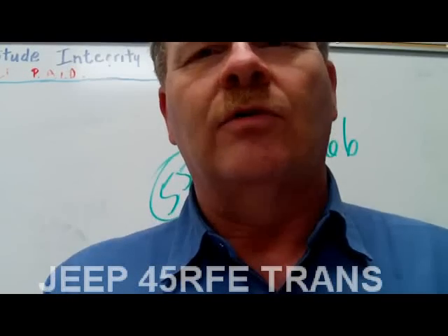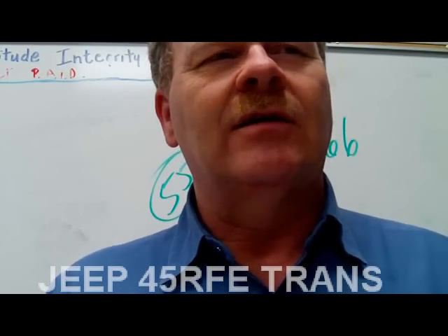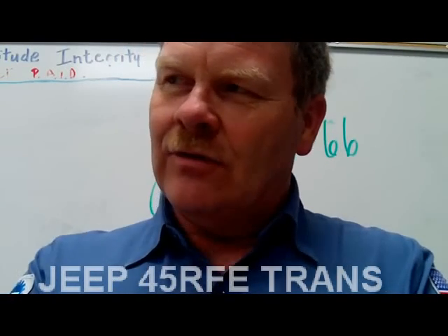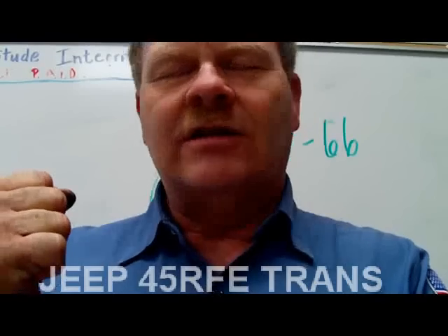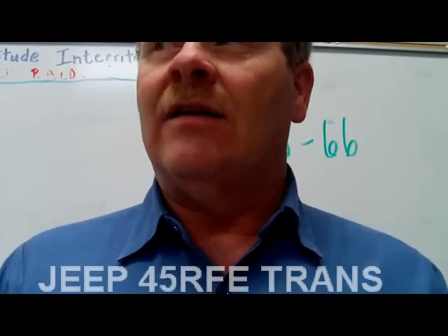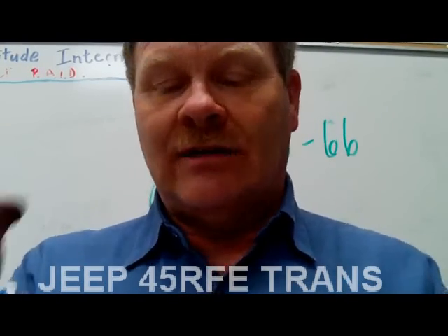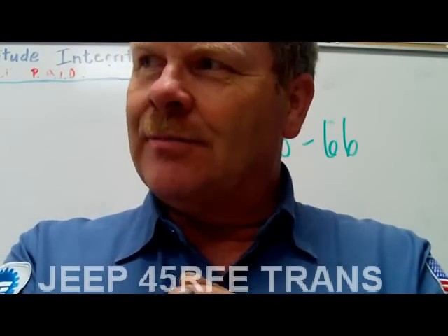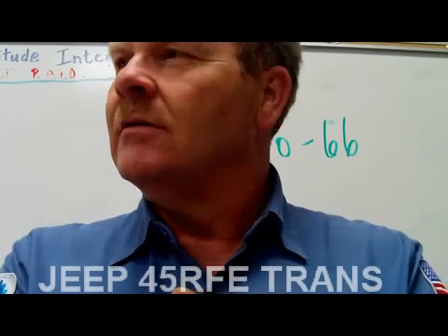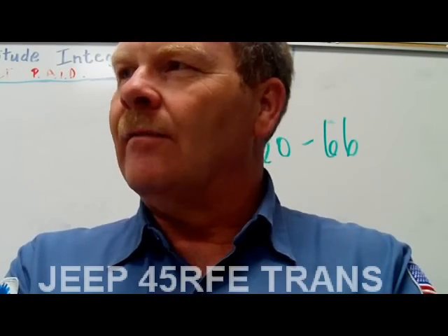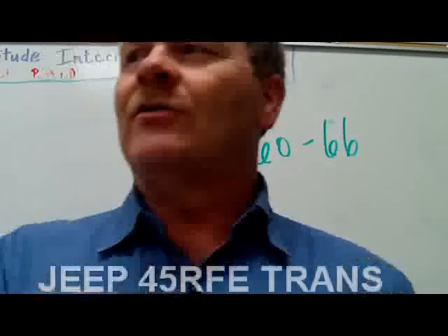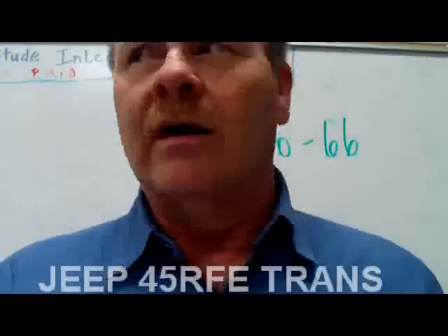Something else you need to remember when you're working on an automatic transmission is, anytime you have splines, like if you've got a shaft that goes into some splines, particularly down in the torque converter, it's a good idea to take that turbine shaft and stick it down in the torque converter and turn it to see if those splines are stripped out or loose. See what I mean? If they are, then even if everything else is good on the transmission all the way through, if you've got the splines wiped out in the torque converter, it ain't going nowhere.